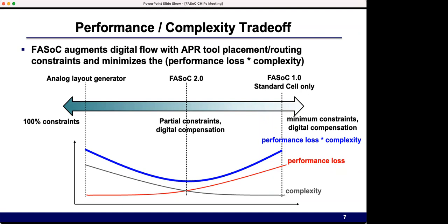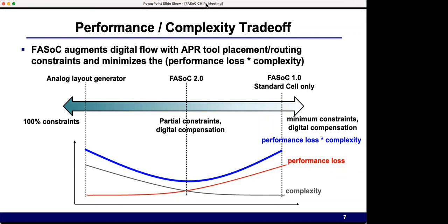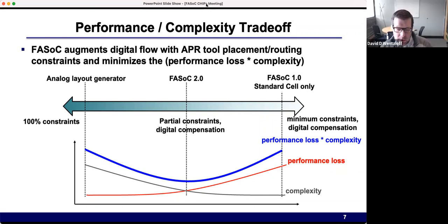Is that similar to what you're doing with the Python scripts? Yeah, I'd say that's similar. Actually, I'll show you an example later of what those look like. Similar to what Mehdi was saying, we would use Python for placing most critical cells, like for example the delay cells, the tri-state buffers and the switch caps in a digitally controlled oscillator. We would place those with Python in an array where they abut next to one another.